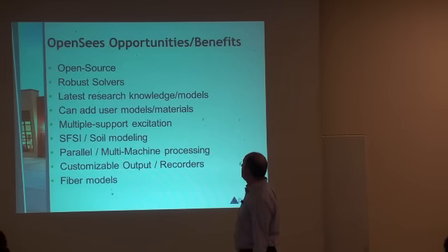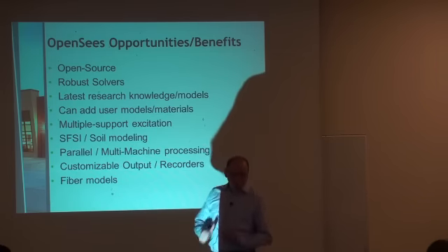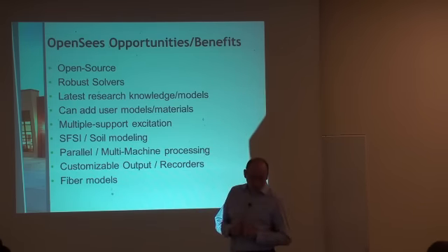So with OpenSees specifically, some of the benefits that I see in OpenSees is it's open source, as you know. It has some robust capabilities. It includes the latest research. You can add your user models. I've never done it, but I assume you can do that and it shouldn't be too hard. You can do multiple support excitation, soil foundation, structure interaction, and soil modeling. This is one main reason we're trying to move more into OpenSees. I think there's another presentation on that.